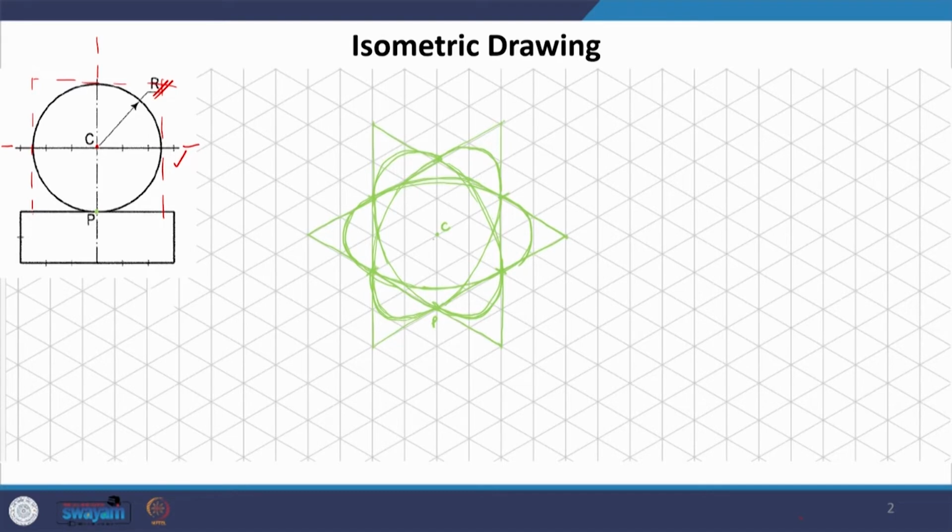If you look at this distance, CP is actually the isometric radius. So, if we are using the isometric dimensions, then this is the isometric radius. Now, we very clearly know that from wherever we see a complete sphere, we will be seeing it like a circle. But if I have to rotate any one of the circles 360 degrees, what will we get? We will actually get a circle, which is how it will be seen in isometric, but what radius?